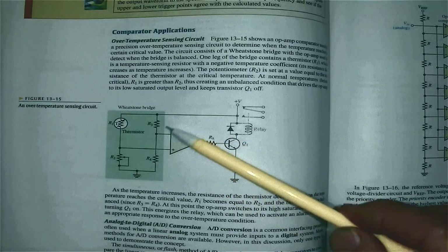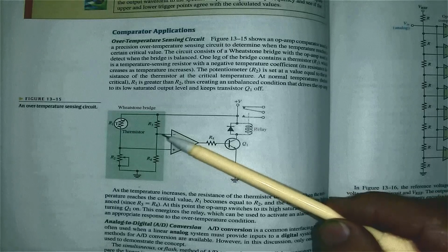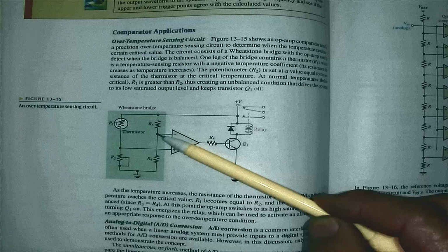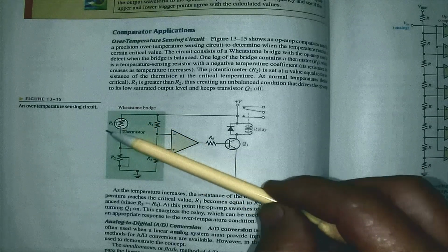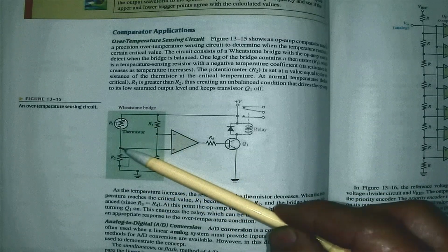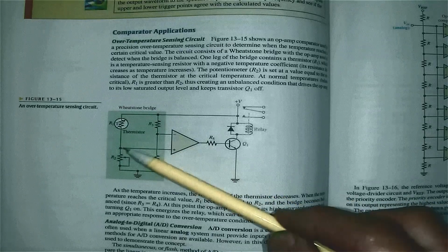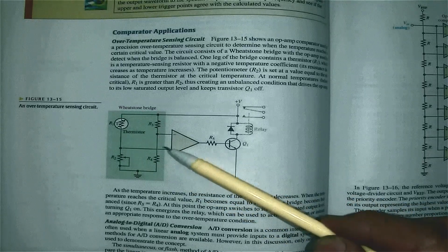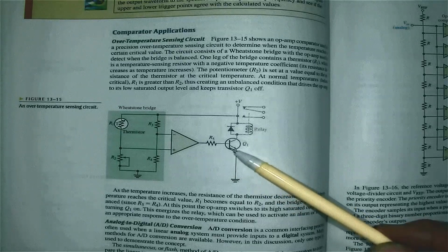First of all, the comparator, R3 and R4 give us a reference voltage. Let's assume this reference voltage at this point is 5 volts. And we've got a thermistor with a negative temperature coefficient. Let's assume the adjustments are such that the voltage here is 4.5 volts. So I have 5 volts for my reference, and 4.5 volts here. That means that is negative with respect to my reference. When it's negative, the output will be negative, and the transistor will be off.